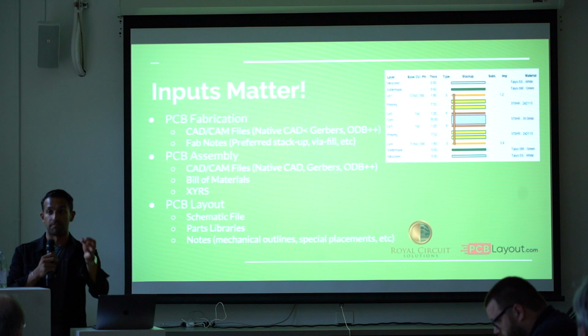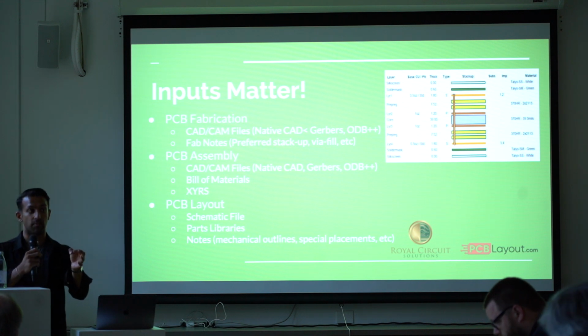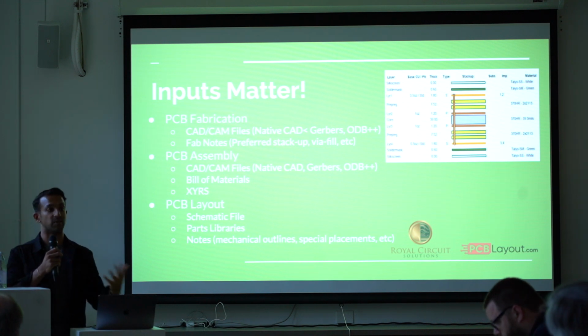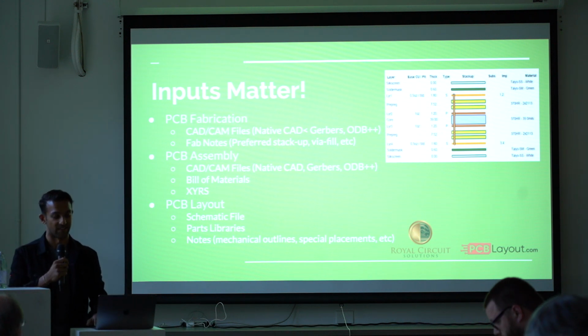Via fill, if you have barrier applying vias, via in pad, they pretty much require epoxy via fill. Not everybody realizes that, and it adds 3 days of time. So be really, really cognizant if you're going to add those things.